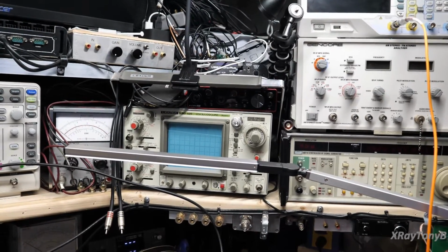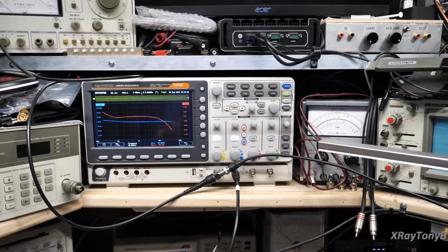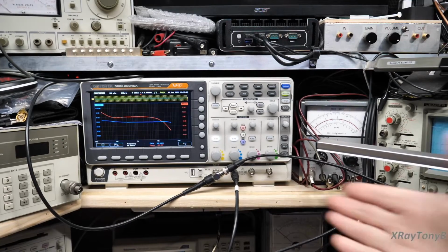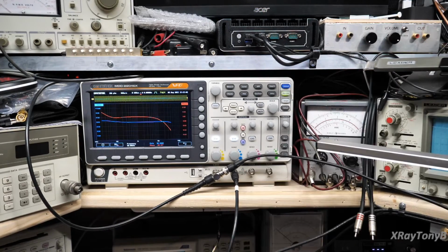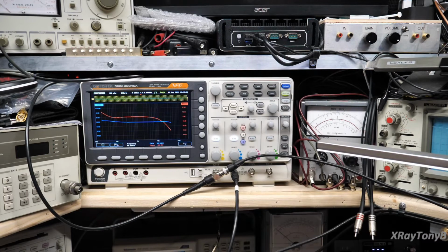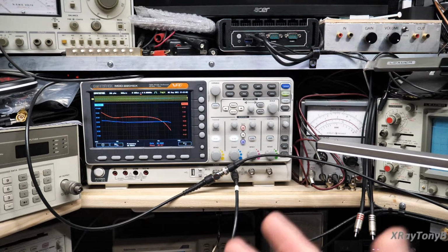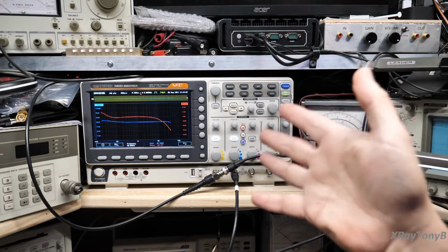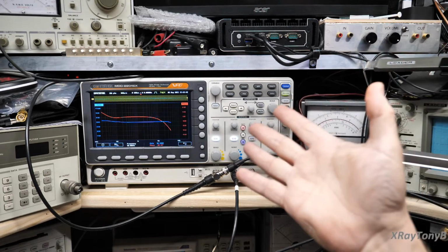Whereas with this MDO, it's an oscilloscope. It's designed to see signals in the volts level, up to 100 volts or so. So it won't hurt anything. If you put your speaker terminals right into the input of the scope, it will just scale itself to it, and it's happy. The other thing is, usually the input of an oscilloscope channel is relatively low noise, and you won't have any of that kind of interference. So it's a trade-off like anything else, but I was very impressed by what this little thing can do.